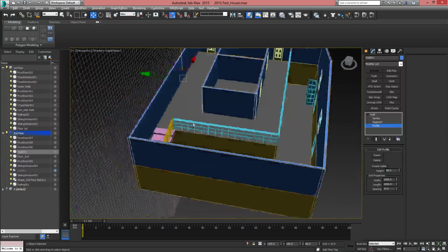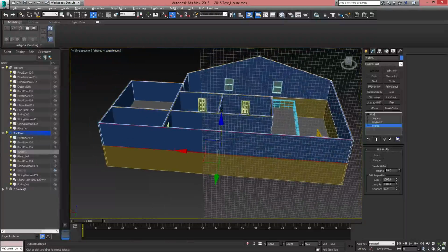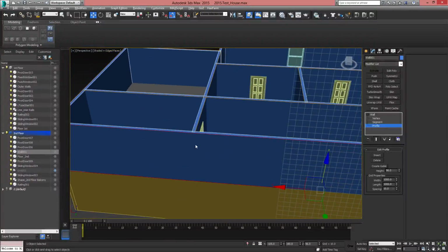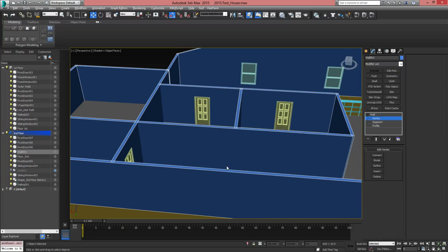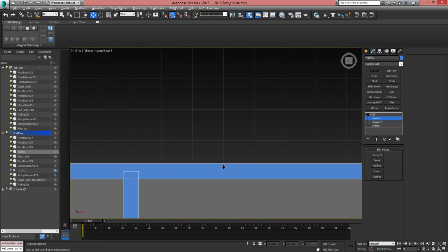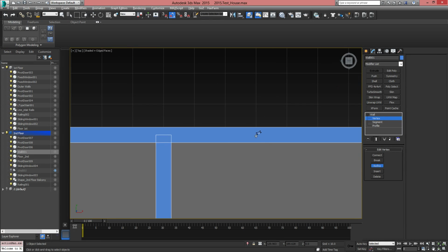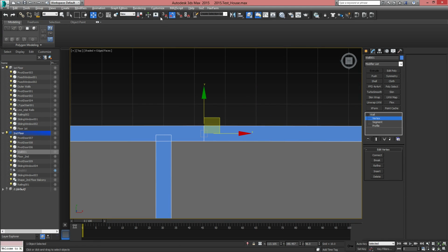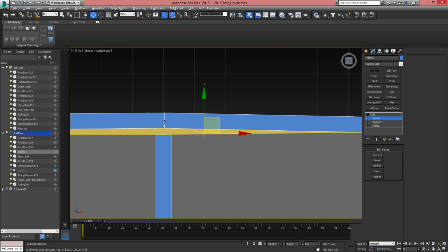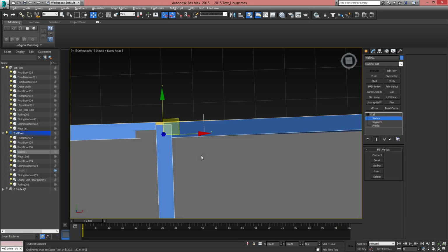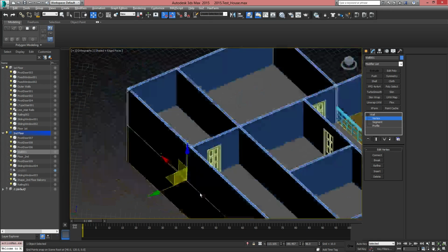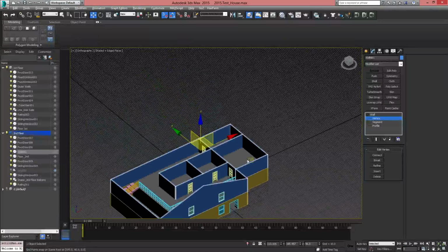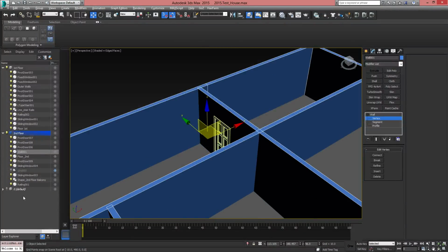I'm going to select this side here, and I want to make sure I separate this division for this wall first before I even do that. So go back to vertex mode, and again, I'm just going to hit refine, drop a vertex here, and move this onto this point. Oh, I don't have snaps on. Turn snaps on first, drop it onto that point. Whoops. It's like something weird is going on here. Looks like my other grid isn't active anymore, so I need to activate that.